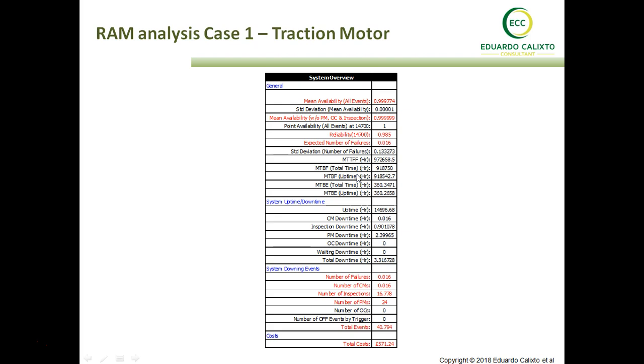Mean time is an average, and of course we need to look at each equipment component's PDF and reliability, in order to understand the pattern of the failure, as well as when we have increasing failure rates, in order to input some scheduled maintenance, non-destructive test or inspection to avoid the failures. And that we already discussed, and that's why reliability, expected number of failures and operation availability will be better.